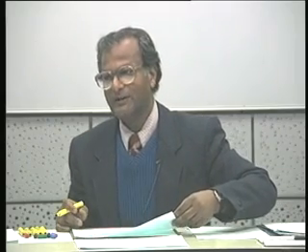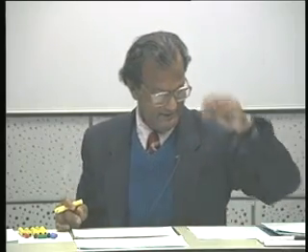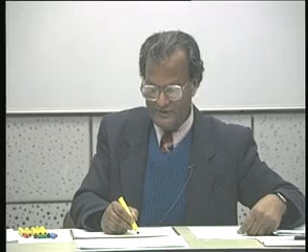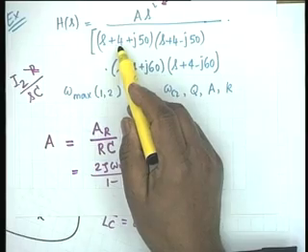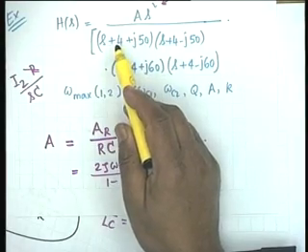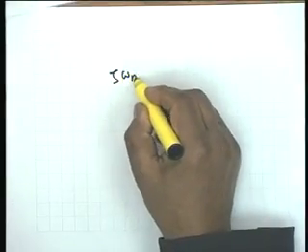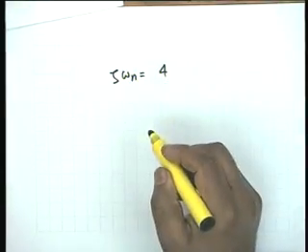Then we shall be able to find everything else. Let us see. First thing is, we notice that by comparing the transfer function, by looking at the pole location, the real part is minus 4 for all the poles, and therefore one conclusion that we get is zeta omega n should be equal to 4.